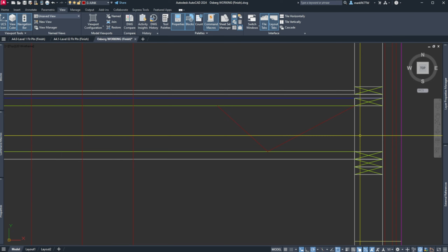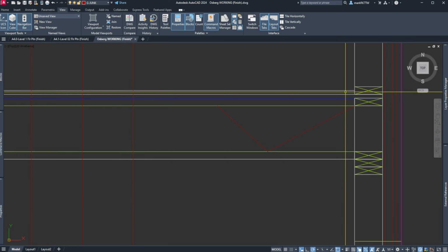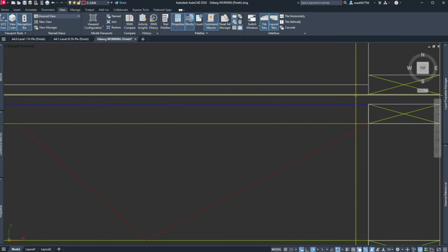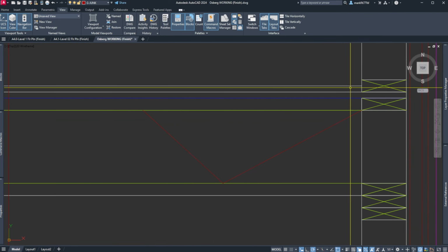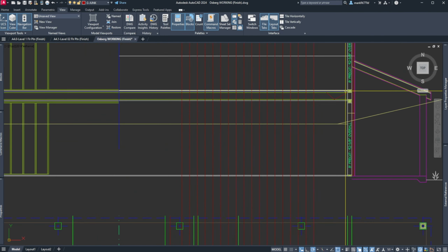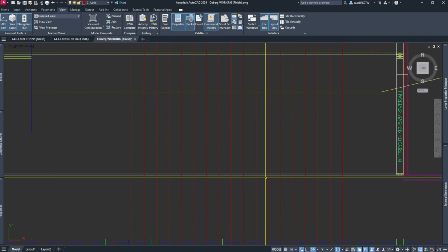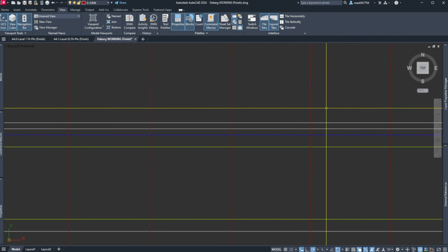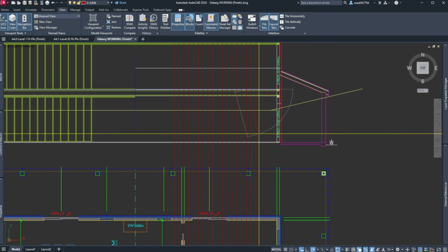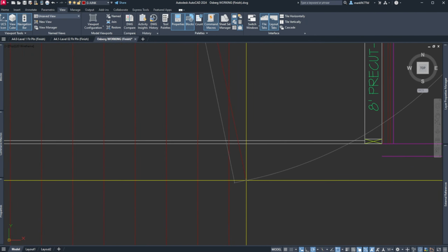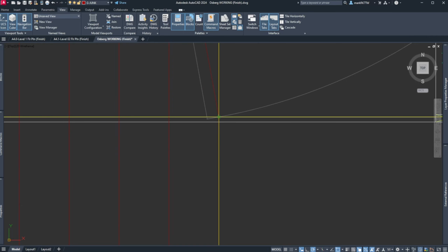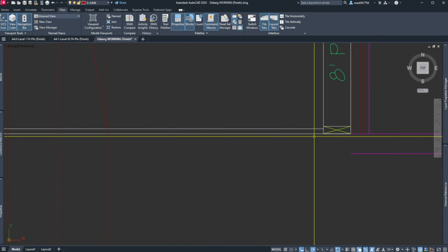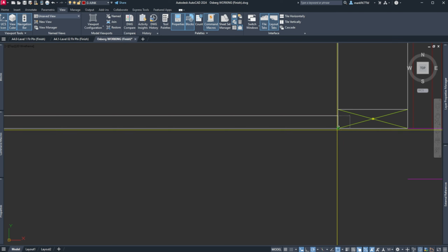whether that be a carpet and pad or hardwood or tile and like some Schluter Ditra, which is a favorite product of mine. And you might be off by a little bit by only using a 3/4. In some cases, it might go to an inch or close to. And it depends really on what material you get, but it's a great number to just kind of work with. So since I know that's my height to my finished floor, I'm going to draw a line from here down to this level, I believe here. And let's check it. So I've got a distance from here to here of 1 inch.